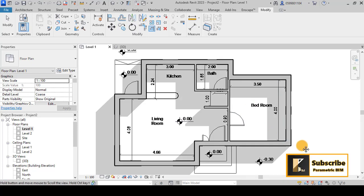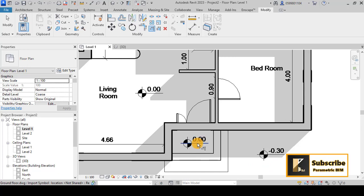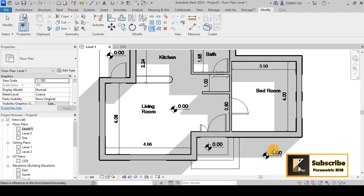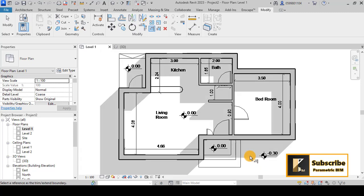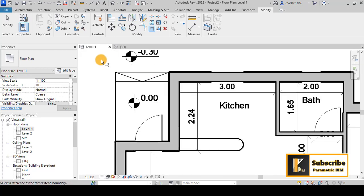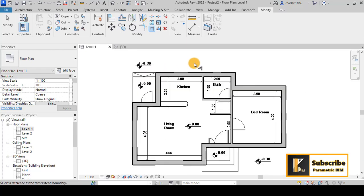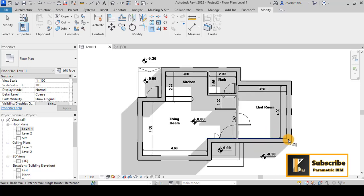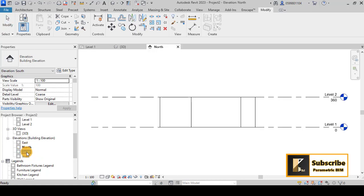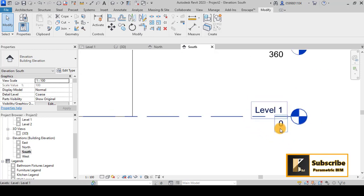Now let's see something important that we are forgetting from the start, that we have here 0 and minus 30 here. So we have another level, which is the outside ground of this small house, because as you see and notice, we have two stairs here, and also here we have two stairs. This means that we have a level which is the outside ground of the house. So I will go now to any elevation, let's say the north or the south, and try to add another one. Maybe this is 0 0.